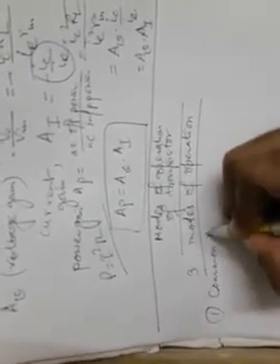First, let us see the common base mode, or CB mode of operation. Let us draw the circuit first. This is the common base mode because this side is the emitter, the bottom side is the base, it is grounded, and this side is the collector.